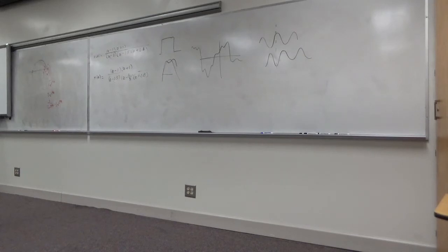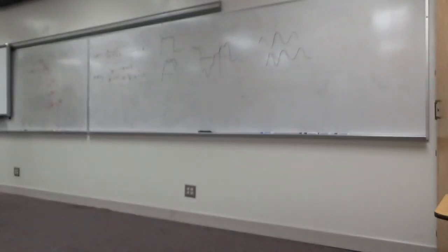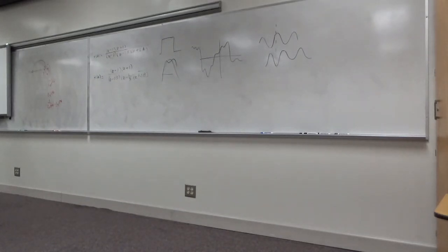Now, you may think I'm making a big deal out of nothing, but very soon, probably week after next, we're going to talk about phase relationships more, and we're going to talk about zeros. What do you know about zeros? Inside or outside the unit circle doesn't matter for stability, but it does matter for the phase response.